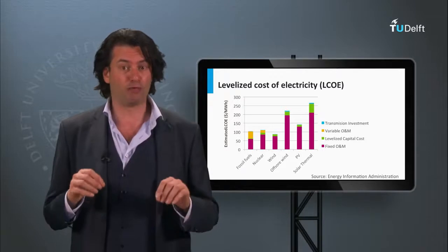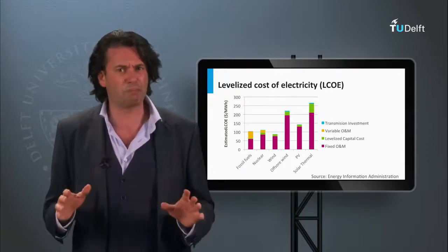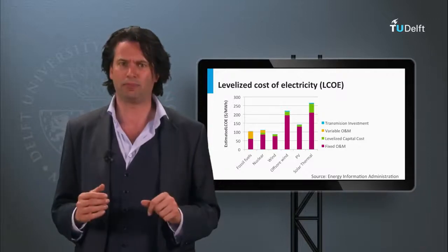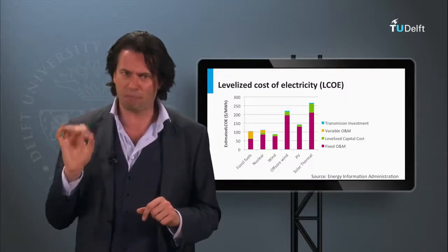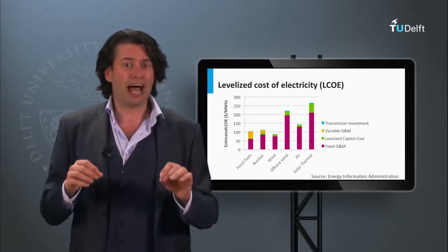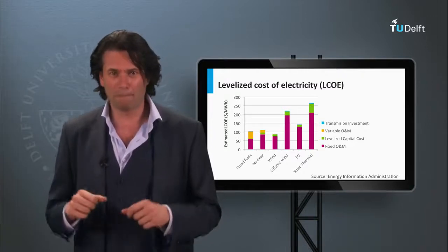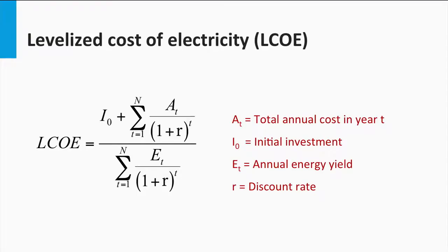The concept of levelized cost of electricity allocates the cost of an energy plant across its useful lifetime to give an effective price per kilowatt hour. It is similar to averaging the upfront cost of the production over a long period of time. The levelized cost of electricity calculation could get very complex depending on the various parameters considered.